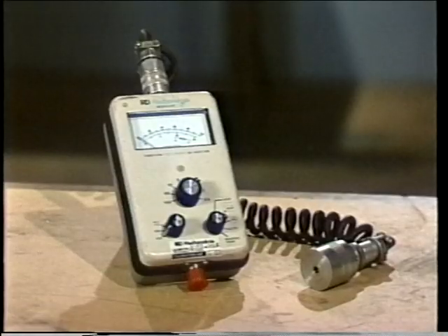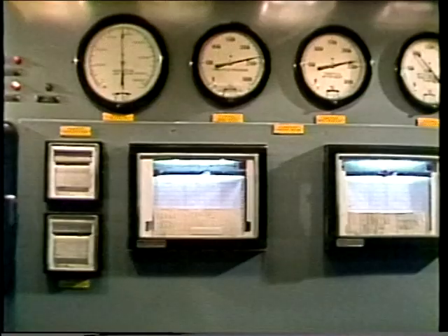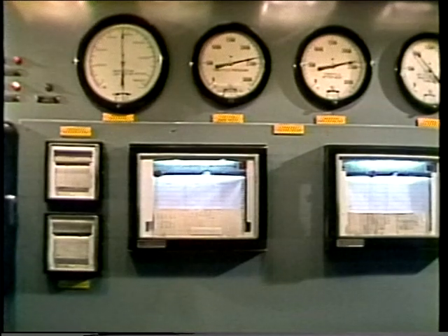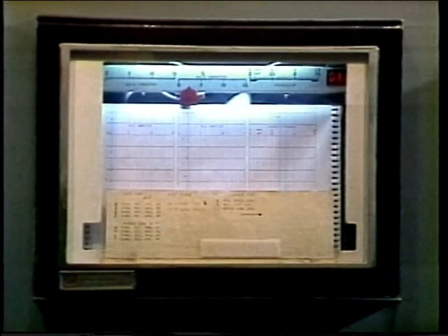However, for the sake of our discussion, we'll group these instruments in three basic categories: vibration meters, which normally provide only overall displacement, velocity, or acceleration meter readings; vibration analyzers, which are generally a little more sophisticated than meters and can monitor specific frequencies so that a detailed analysis can be performed; and vibration monitors, which are normally permanently mounted instruments that are used as a visual indicator and a safety instrument. Vibration monitors are not normally used for vibration analysis.